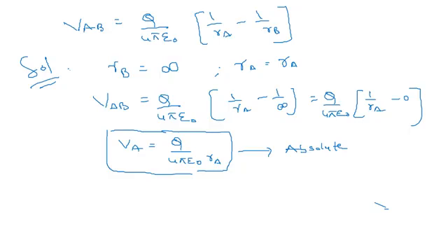Instead of a potential difference, it is more convenient to express the absolute potentials of various points in the field. If you take any field, you can take various points. Such absolute potentials, as you see here, VA is the absolute potential. These are measured with respect to specific reference positions, and such a reference position is assumed to be zero potential. Similarly, in a cathode ray tube, the metallic shield around the tube is taken as zero potential, and with respect to that reference, the potentials of various points are measured. So this is the absolute potential